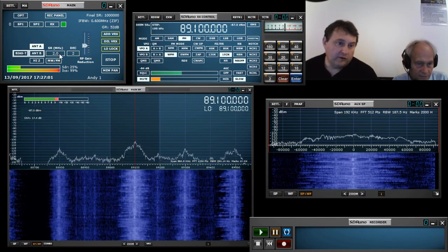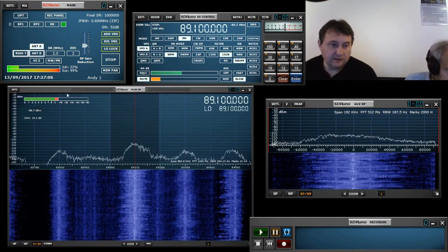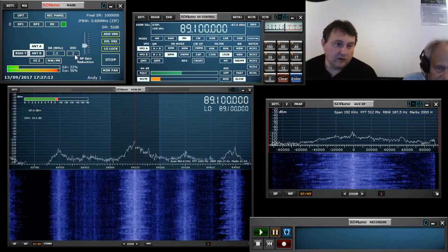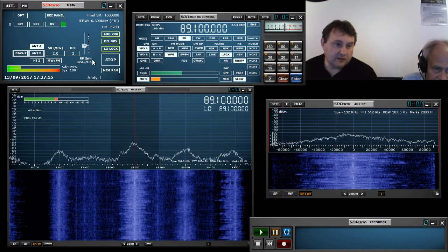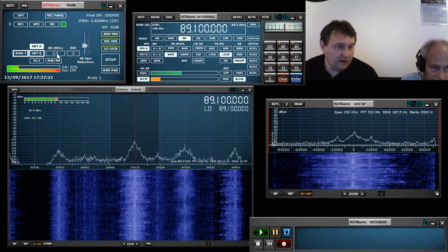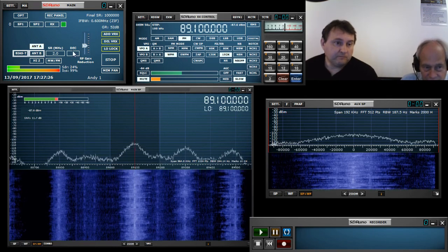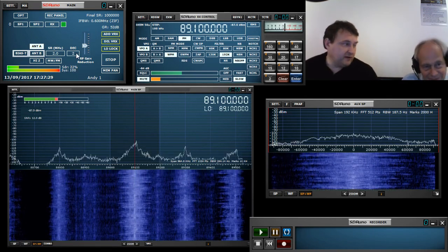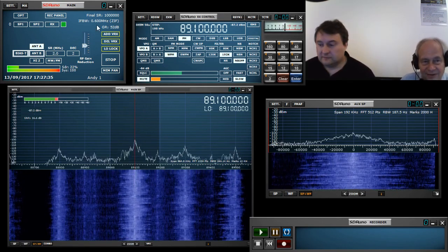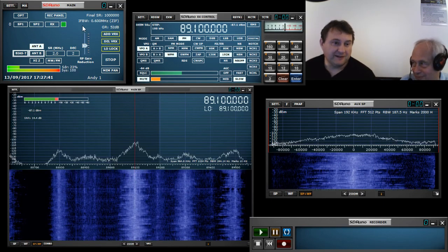So on the main window, you have a sample rate field, SR, which you can specify between 2 and 10 megahertz in 1 megahertz steps. And then next to that is the DEC window, which you can specify as a decimation up to 8. I think in future versions we're going to be able to increase that amount of decimation. Then you divide the sample rate by the decimation factor, and that will give you your final sample rate, in the top right hand corner, final SR. That's of course in hertz. This is all in hertz, unfortunately. We get a lot of comments about that.